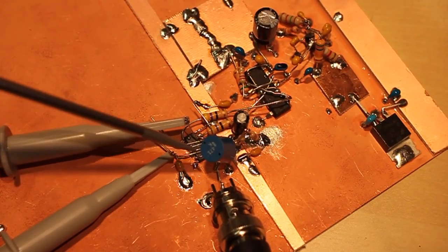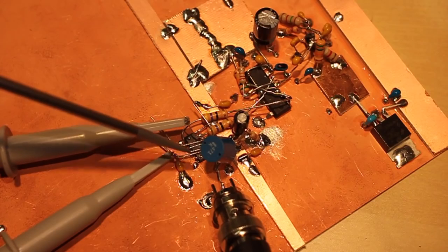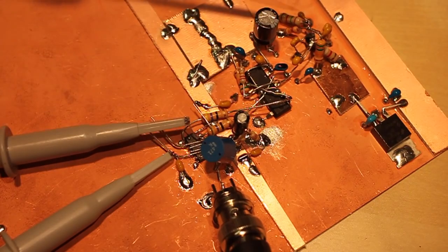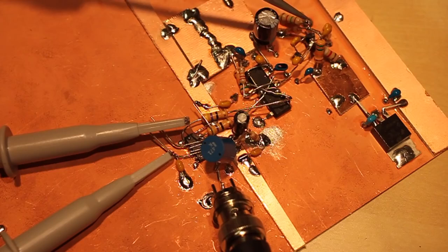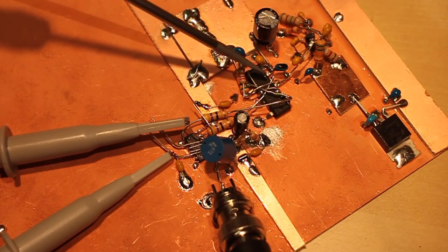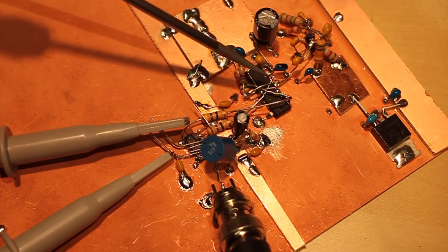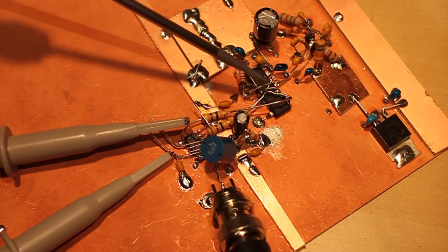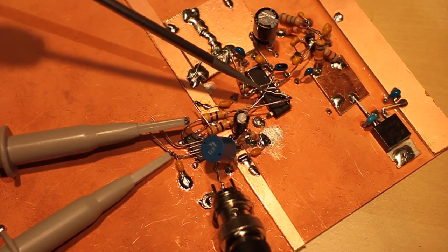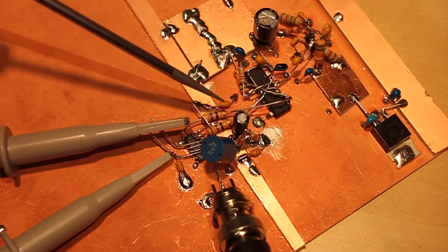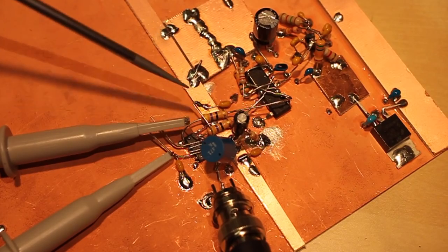So I've added that mixer circuit here on my receiver board, and as we've seen from previous videos, I have a 28 megahertz oscillator that's being fed into a dual D-type flip-flop, and that divides the frequency by 4 down to 7 megahertz and provides the I and Q quadrature local oscillator outputs that I'm feeding into the mixer.